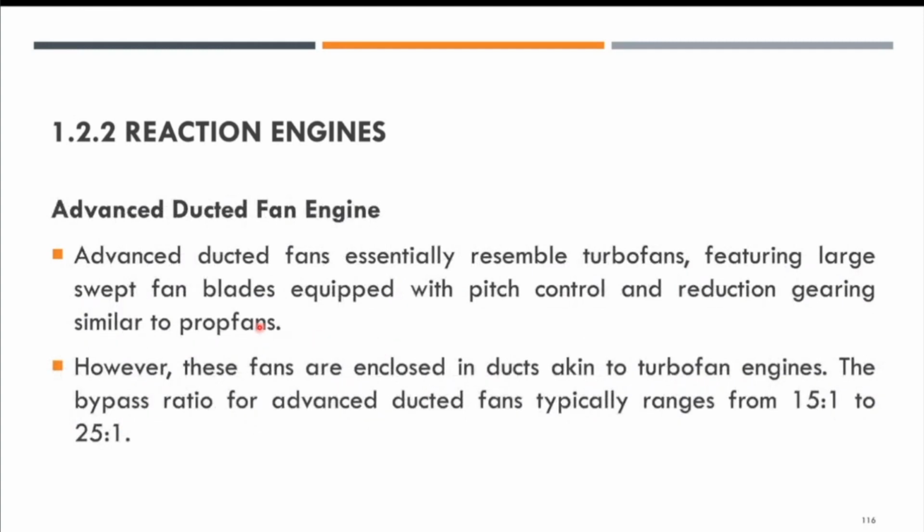Okay, the last one is advanced ducted fan engine. For this type of engine, advanced ducted fan essentially resemble turbofan. It is part of the turbofan, but it is called advanced ducted fan, featuring large swept fan blades equipped with pitch control and reduction gearing, similar to prop fan. However, these fans are enclosed in ducts compared to prop fan. Prop fan is external. So for this advanced ducted fan, it is enclosed within the engine nozzle.